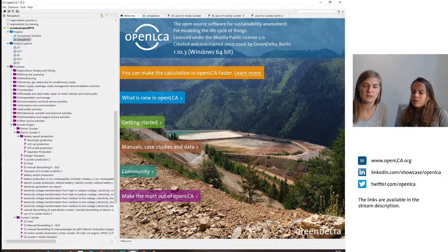So I'm not sure if I fully understand. So basically, CREAT, you can say, is also a database and also a model for calculating the carbon intensity of transports. So it would mean, here Thais was working with Ecoinvent 3.6, and yes, you can use it in openLCA. So if you have a license or any kind of license, you can import it to the software as a basic database for your background data, as Thais now also used it, and then you can model your foreground system here.